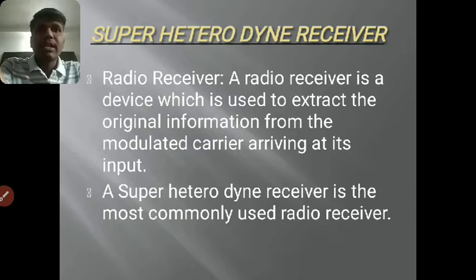Rectification is used in demodulation when the modulating signal of the carrier wave is 180 degrees out of phase, so the upper and lower portions of the waveform go through the rectification process. The rectifier converts the modulated signal so as to remove one half of the waveform and keep only a single waveform for filtration. Filtration gives the pure demodulated waveform. Since this detection process is used for amplitude modulation, it is called the amplitude modulation detector.